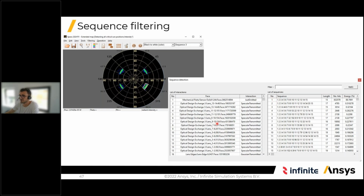And here on the left, you see the actions that belong to the sequence. So each action is a reflection or a transmission at a certain surface, and you can also see at which object that interaction happens. So it happens to be that sequence number 3 is the one that causes these annoying hotspots at the edges. This is what we want to get rid of.